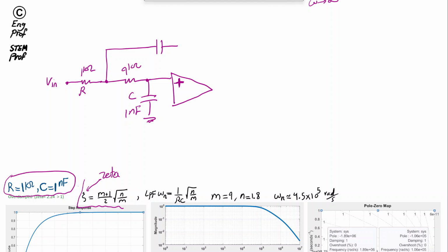And then we have the connection to the op-amp. Depending on the target speed or target frequency, the proper op-amp with the proper slew rate and bandwidth can be selected from either Analog Devices or Texas Instruments. They have a good selection depending on what frequency or slew rate you have in mind, or even what sort of noise performance a designer has in mind. So let's consider this a buffer, and then at the output we have V out. This is the form of our Sallen Key filter, and it's a low-pass filter in this case. So second order Sallen Key low-pass filter.